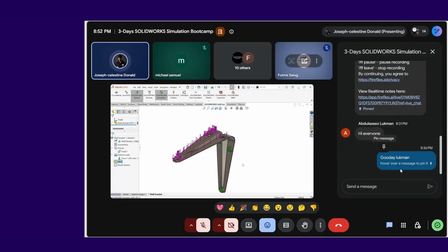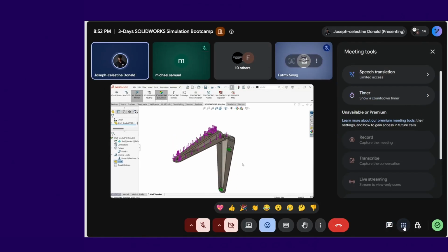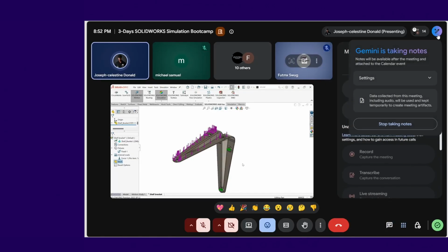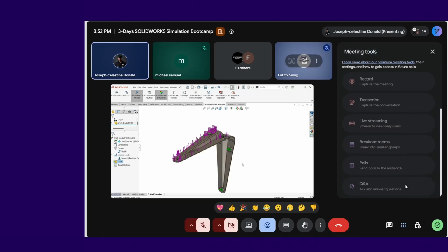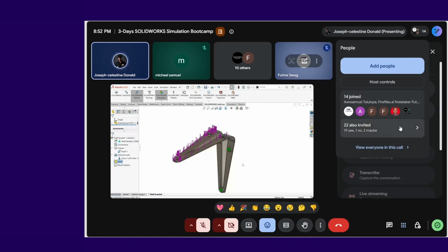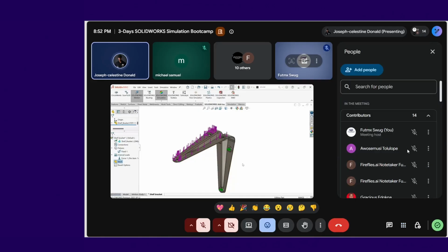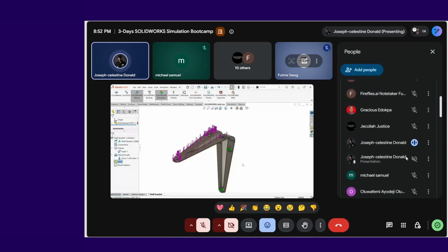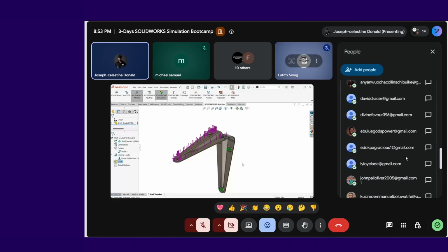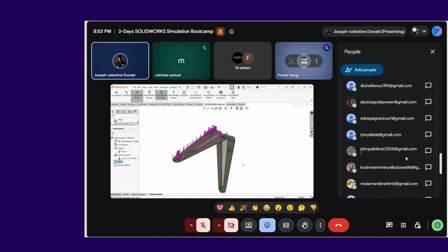The shapes vary, depending on how fine you want it to be. The thing to notice is that your mesh directly contributes to the accuracy of your results. A coarse mesh means your model is split into bigger components, so there are fewer, it meshes faster and solves faster, but your result is going to be a bit vague.